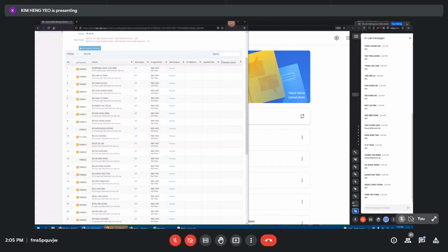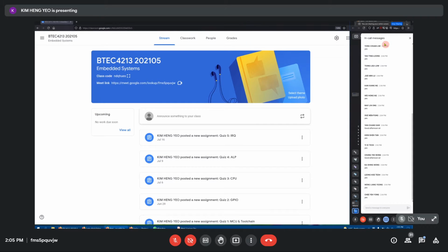All right, so today we are going to review the lecture materials, the lecture videos. Very interesting topic on interrupts. Interrupts is the heart of microcontrollers. Interrupt is the mechanism that allows your microcontrollers to respond quickly to any events that happen. And interrupts is what made the ARM Cortex processors so popular, so powerful because of the interrupt system. And we shall see shortly why it's so good.